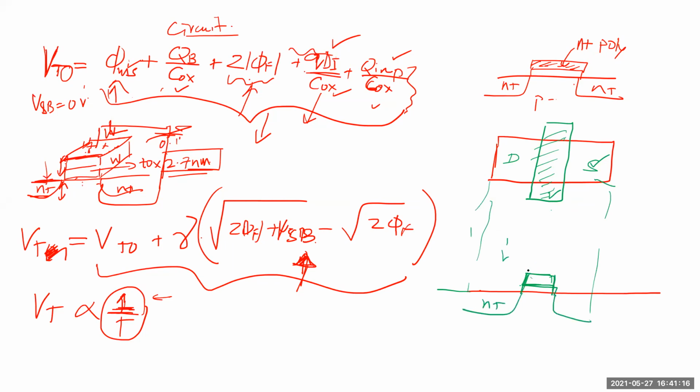Yes, sir. And the self-alignment is because this poly is there. It stops the N plus, but in the process, this gets doped N plus. And that's what you want. The silicide is after this. This is purely bombarding. Silicide has nothing to do with the N plus poly. Silicide is another layer on top of the poly, a very thin, highly conductive titanium or whatever silicide layer they use, and it's also on this as well.